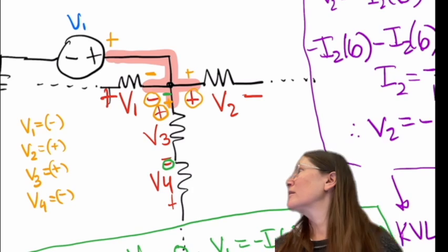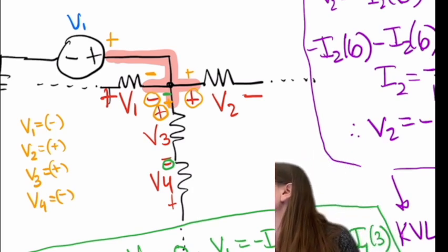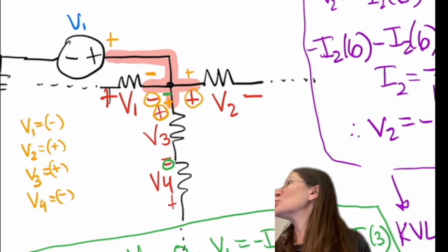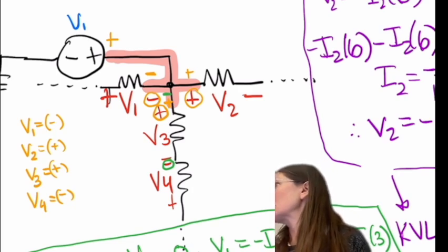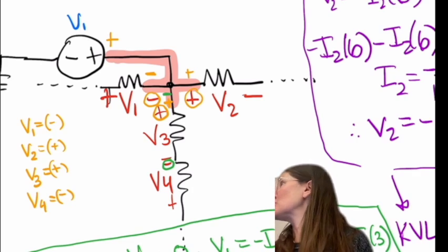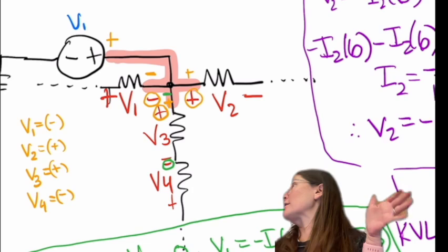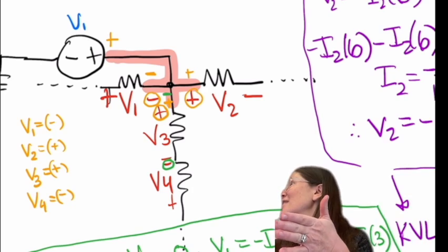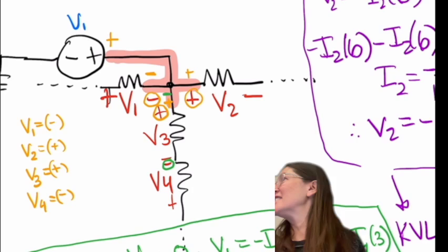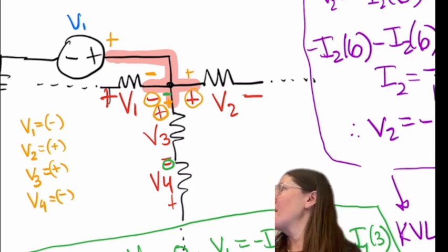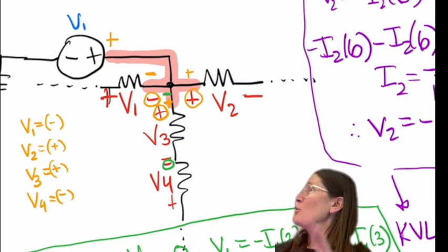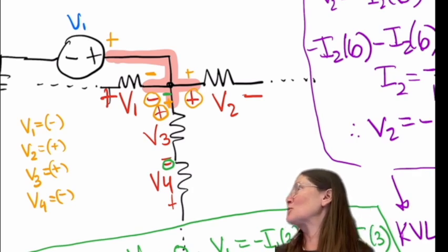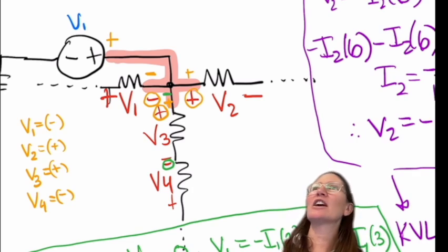So I guess I'm just a little confused. How do you assign the polarity to the resistors? If it's labeled, it's already assigned, and then you can choose which direction you want to label the currents. If it's not labeled, then you can also choose the direction of the voltage. And then you solve that circuit, however you've labeled it. You just stick with that labeling, don't change it. Does it have to be consistent in the same circuit? It does need to be. Once you've labeled it, solve every variable in that circuit with the same labeling. Don't change.